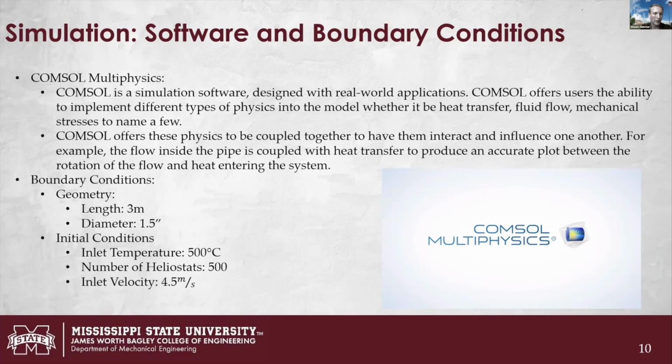Also, COMSOL allows these physics to be coupled together. So, for example, you could have a turbulent flow inside the pipe, as we're going to show in the next couple of slides for simulation results. There's going to be an inflow of the heat transfer fluid, but this flow is going to vary. It's going to have low velocities with high pressure, and high velocities with low pressure, and so on and so forth. And it's going to be coupled with the heat transfer to produce an accurate plot of what the temperature distribution is going to look like in the system.